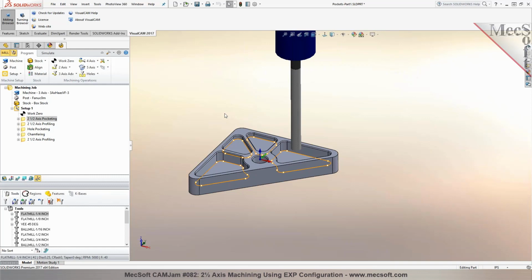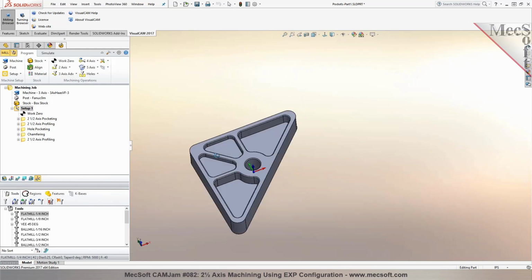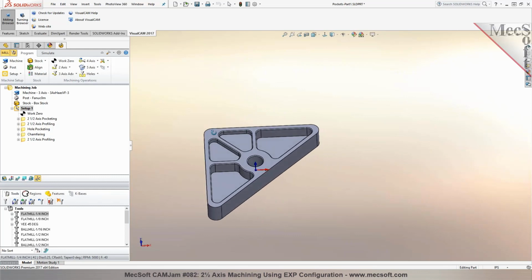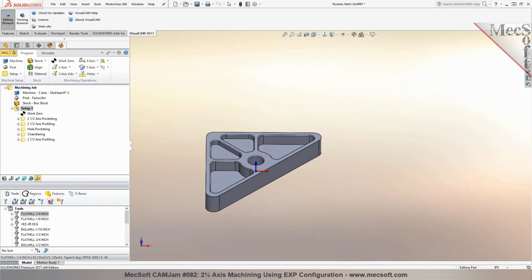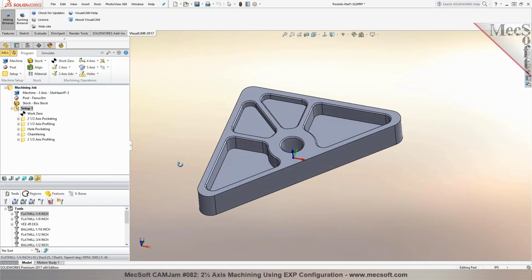At that point, I need to give some indicative information to him, such as which point I have defined as the reference point, how I am planning to fix the part on the machine, what the order of the tools in the tool changer is, and which tools are defined on which tool number.